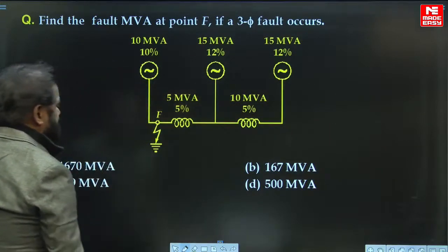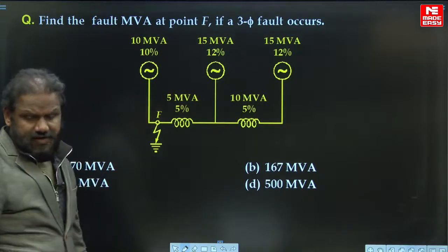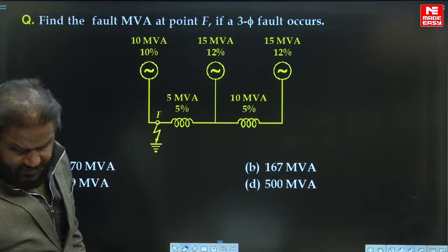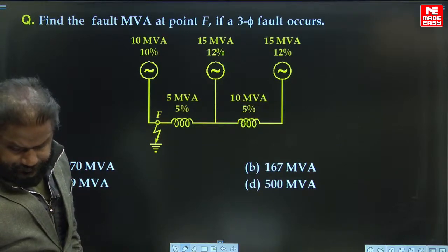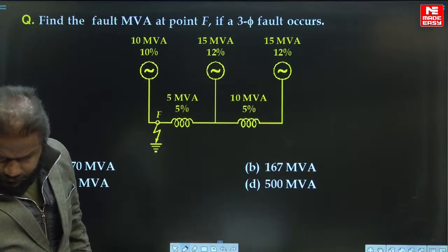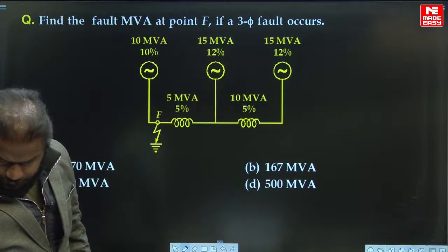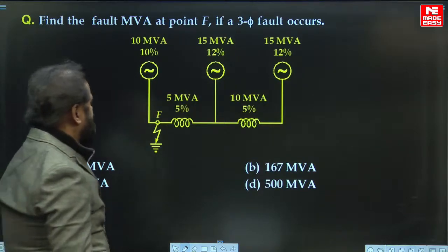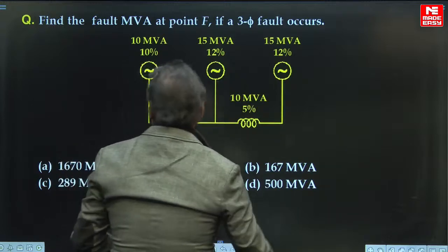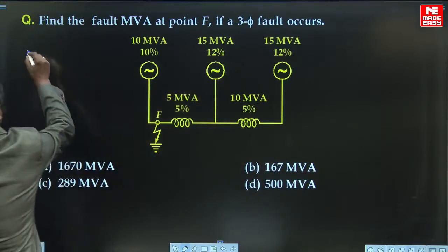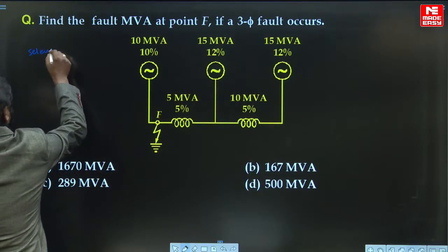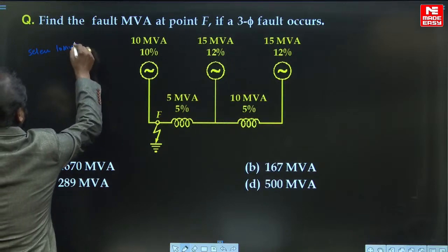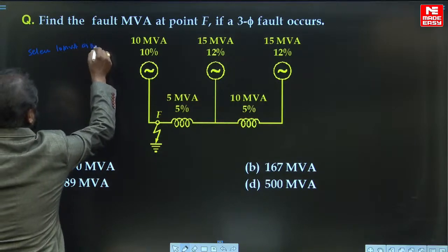Okay, in this the fault has occurred. Then what is the equivalent reactance? Here, take one thing as a base: select 10 MVA as base.